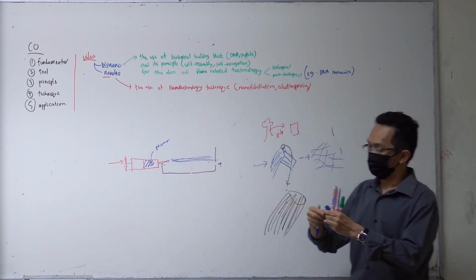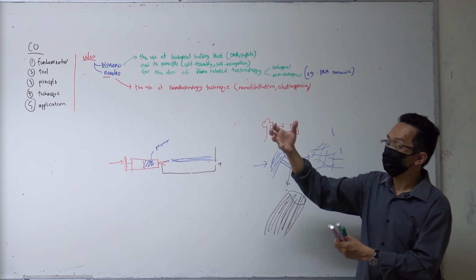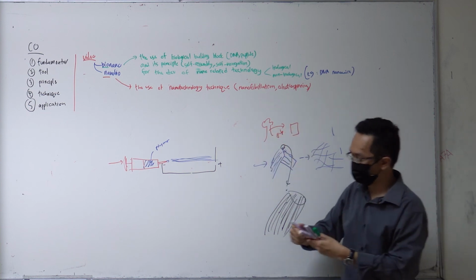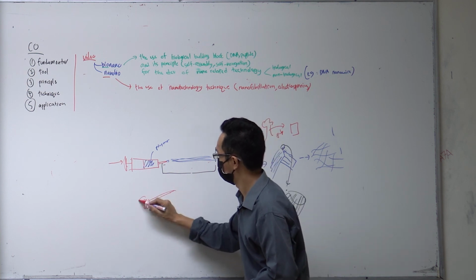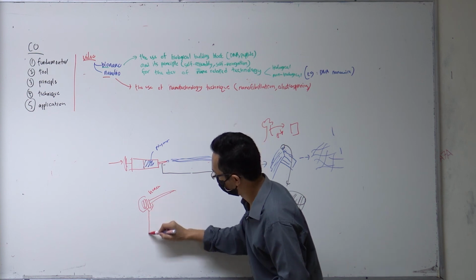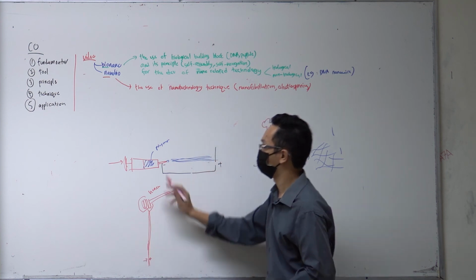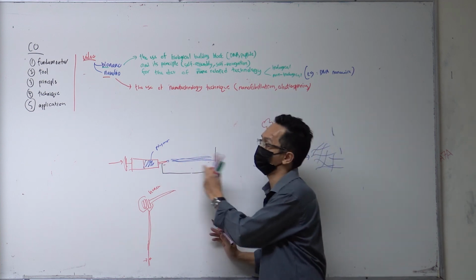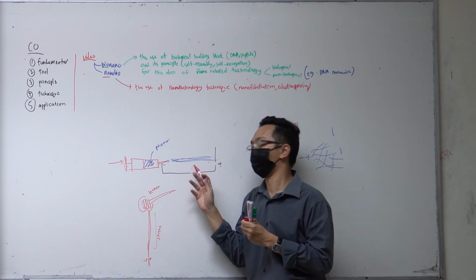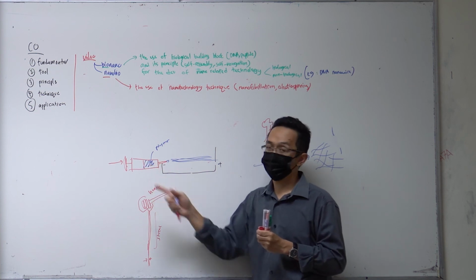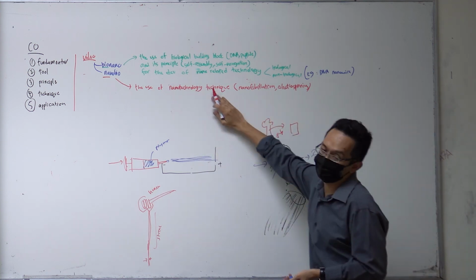because of the distance, it is as if you want to pull something. When you have a polymer and you try to pull it down, it becomes thinner and thinner. You have a melt polymer, or just to give you the idea, you know the honey. If you take the honey and put it like this, you see the honey will drip, and the longer the distance, the thinner the drip becomes. So that's the principle of electrospinning. They use electric potential difference to force this stretching, and by that you get a strand of fiber that is very thin. From a liquid polymer, you get a fiber. So that is basically one of the nanotechnology techniques that you use.